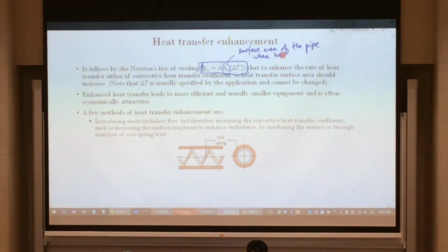where heat is transferring either in or out, depending on which side is hotter and colder. Right. Note, As is not Ac. Ac is a cross-section of the pipe. So if you have a pipe, cut it, look at the cross-section, that is your cross-sectional area. As is that if you have a pipe, and that's internal surface area of the pipe, that is As. So these two refers to the different areas.